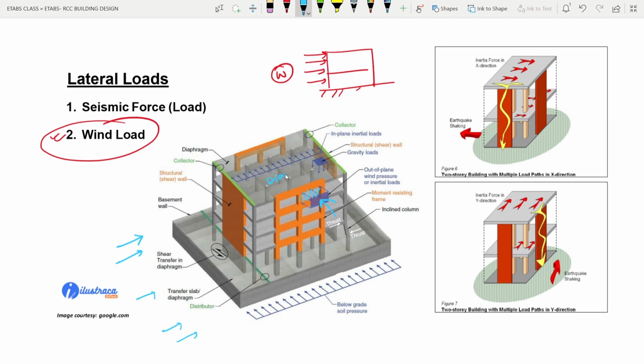Okay, and as it is transferring the lateral force, that's why we call this particular element a diaphragm. Let me write it here properly. We call it a diaphragm. What is it doing actually? It is taking the lateral force from here and transferring it to the vertical members, the members which will actually be resisting the lateral force. So we call the floor slabs our diaphragm.